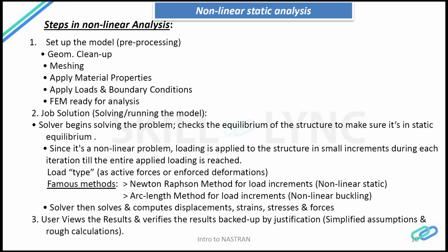Then the nonlinear solution within the solver will start its own process. It will have some methods to follow. Some of the famous methods are the Newton-Raphson method for nonlinear static problems and the arc length method for buckling problems. It will apply the load in very small increments. For example, the total load on the structure is 100 newtons. Suppose you have specified to the solver, in the options while running the model, that you want your load to be applied in 10 increments. Then each time the solver will apply 10 newtons.